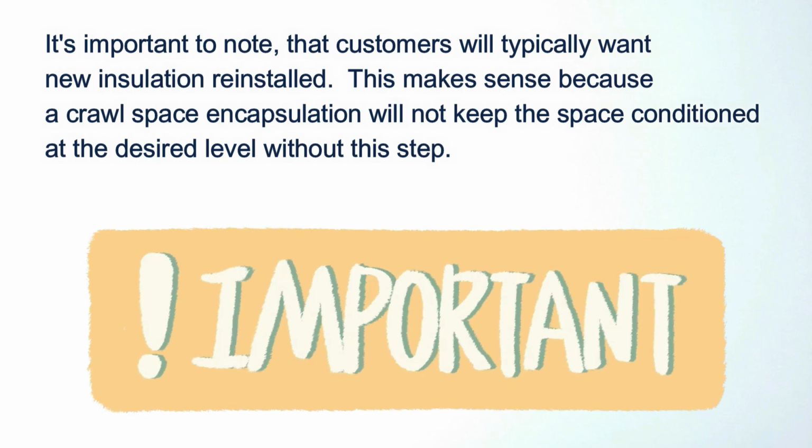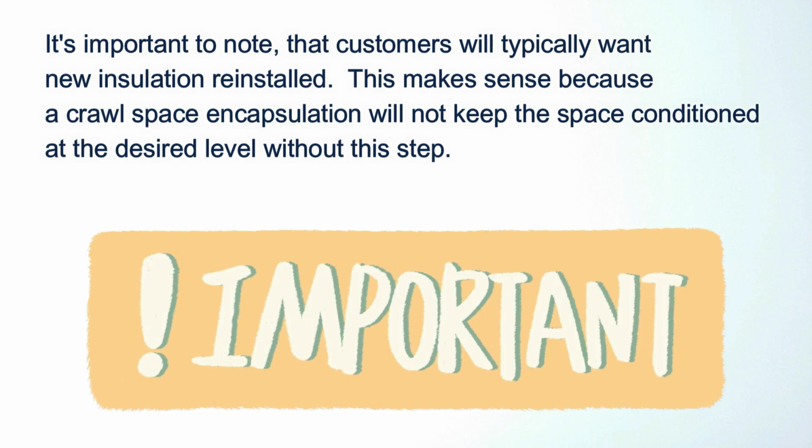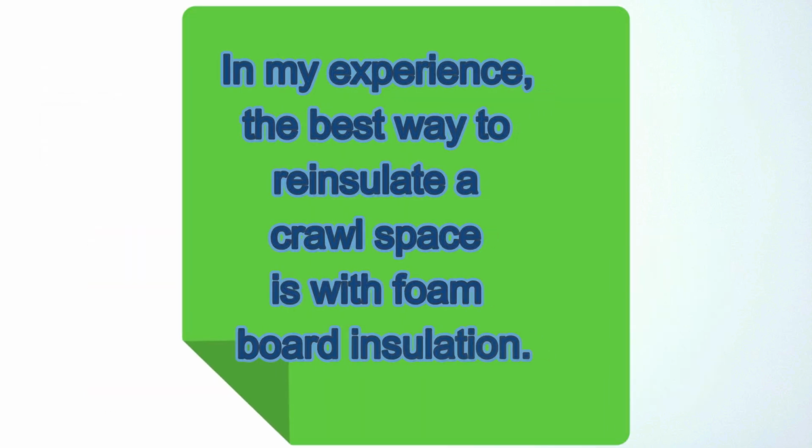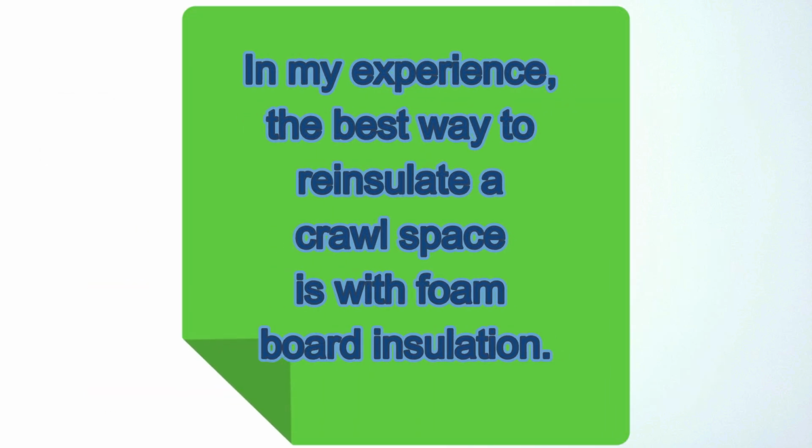It's important to note that customers will typically want new insulation reinstalled. This makes sense because a crawl space encapsulation will not keep the space conditioned at the desired level without this step. In my experience, the best way to re-insulate a crawl space is with foam board insulation.